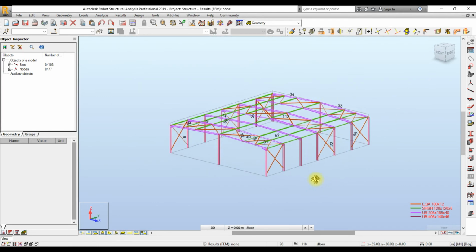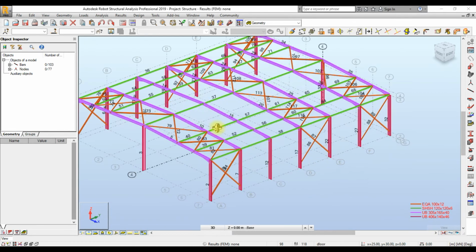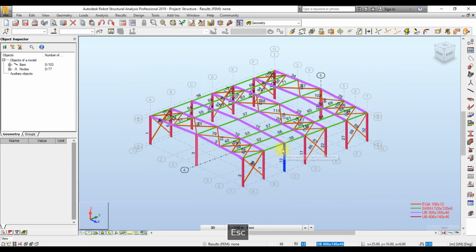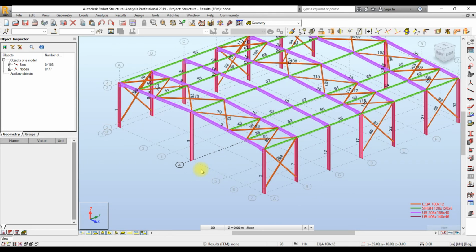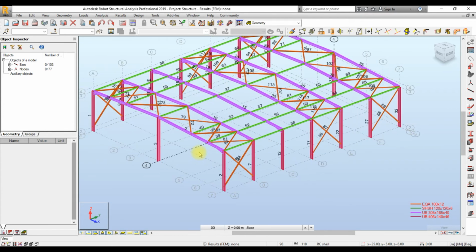So now what we have left is creating our loads. We are going to create our load cases, which are the ultimate and the serviceability limit state. But for this kind of structure, just the wind will act mostly on it and nothing more than the wind, and just the self-weight of the structure itself, which is more crucial. So the serviceability limit state is the function of the structure under maintenance or the appearance, which can be reversible or not reversible if you have some damage to it.